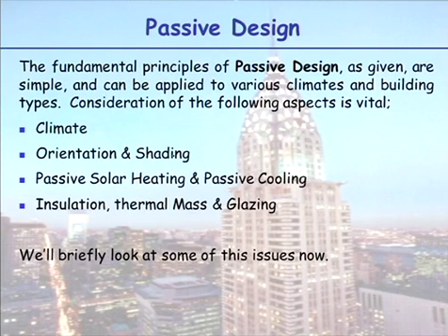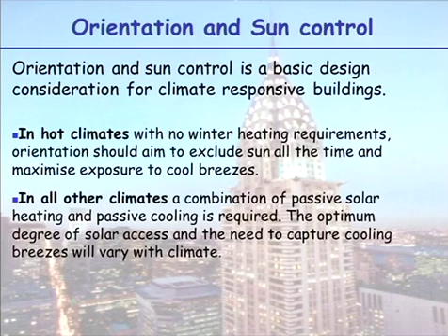So just as the general public, you should be aware of these things. So let's look first at orientation and sun control. In hot climates with no winter heating requirements, so up north, orientation should aim to exclude the sun all the time and to maximise exposure to cool breezes.